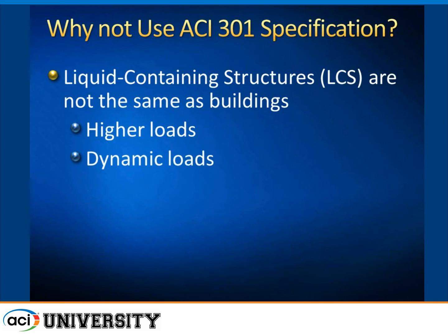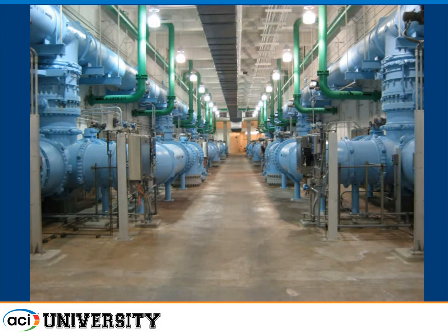We have dynamic loads. The water's flowing in and out. Certainly in seismic, we have sloshing. A large mass of the contents are being carried by the structure of the tank. And this is a gallery, a very large water treatment plant. But you can see we have a lot of big pipe. For some reason, they like to run pipe through walls so it can get into the inside of the tank.